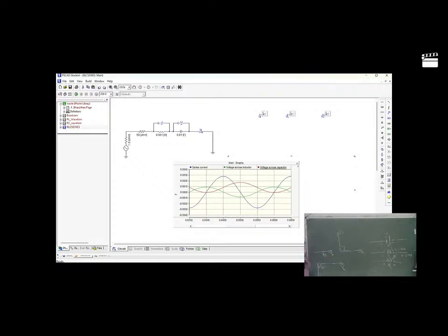You got the point? Now we combine all these three elements in series or parallel. What we have to remember is that we see the voltage across each element and the current across that element, then consider the phase angle, and then we get the phasor diagram of the entire circuit.